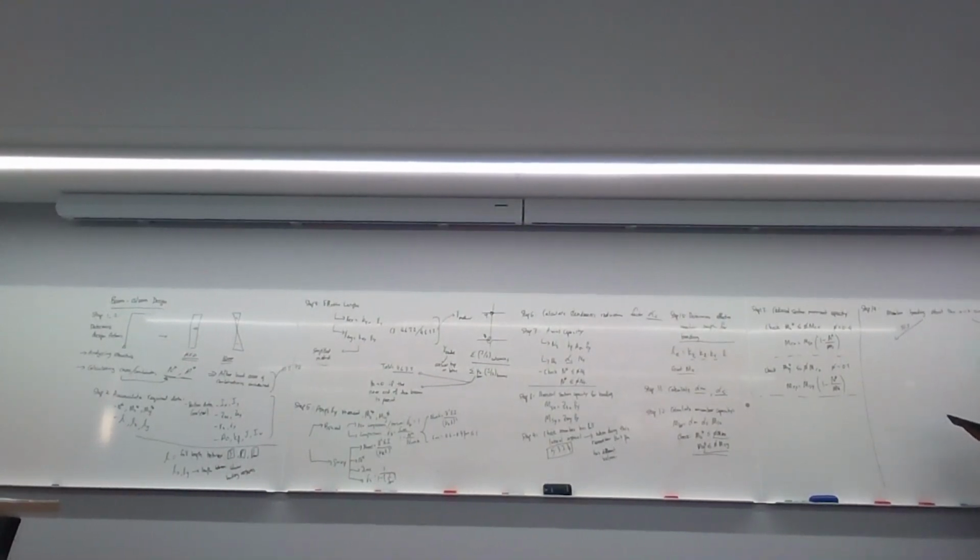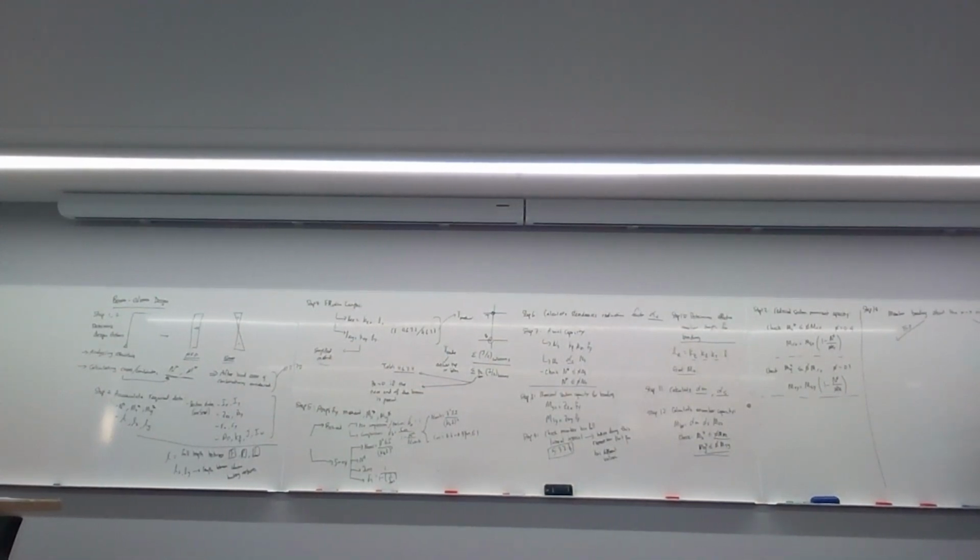If your answer is yes, let's start with no first. If the answer is no here, then check in-plane capacity requirements. Miy equals Msy, 1 minus N star over phi Nc, where phi is equal to 0.9.